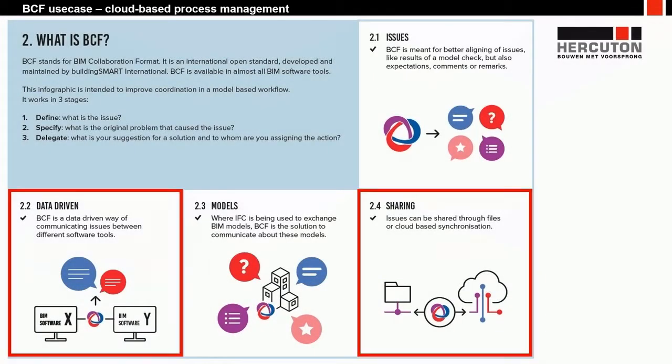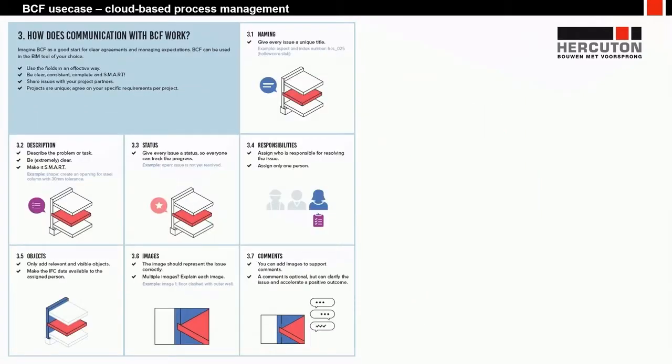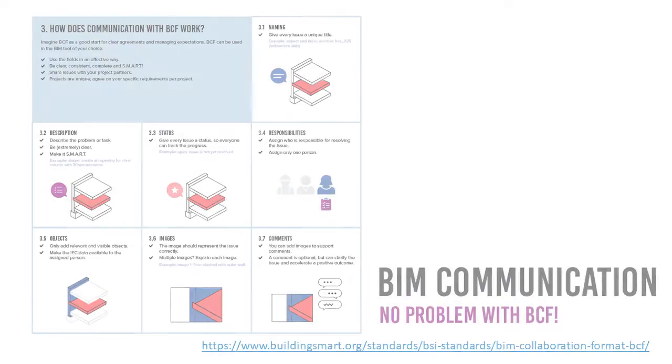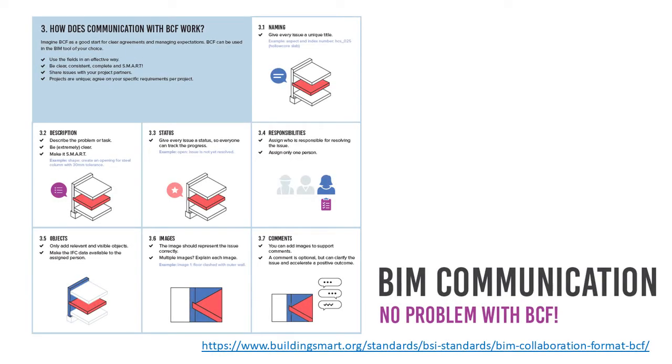So what we did just now, look at data-drivenness by transferring the BCF into Solibri and BIMsync, and using status and comments in our BCF to communicate these tasks within our project team. So that's what we did. It's a little bit different than communicating on the building side. We use our tasks for our planning and use BCF to communicate this. So this will give an insight on a little bit of a different way of using BCF, but maybe you are inspired to do the same.